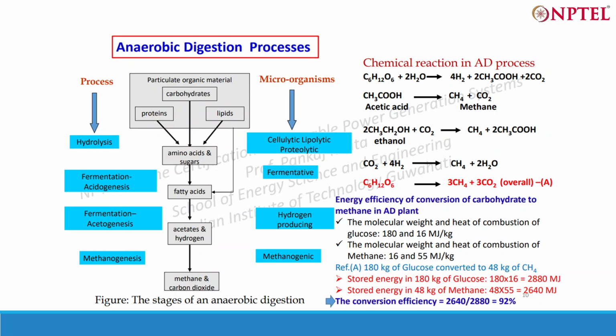Okay, then this organic feed is taken to the slurry preparation chamber where water is mixed and a specific TS ratio is maintained. At that TS ratio the slurry goes into the biodigester, and in the biodigester it remains for a specific period of time depending on the type of feedstock. After that period, biogas is produced, and whatever is left, the leftover digestive slurry, is transferred to a digestate storage chamber